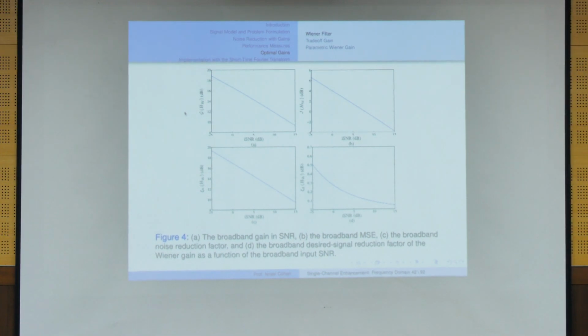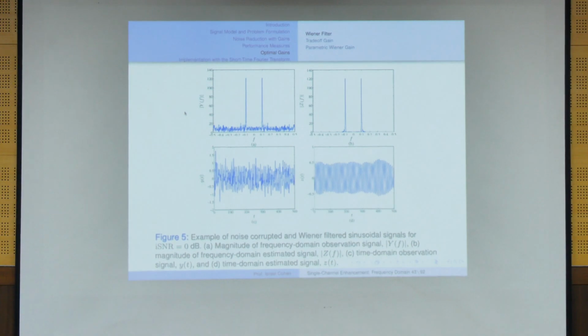But if you remember, we did something similar in the time domain using a filter of 30 samples. Here, when we go to the Fourier transform, we work with the whole measurement of 500 samples. So we can obtain a better performance. Okay, so here we see a realization of the noisy signal. So you see these two spikes. It looks like spikes, but it's not exactly spikes. It's a Dirichlet kernel around each point.